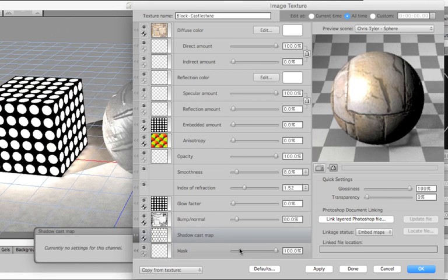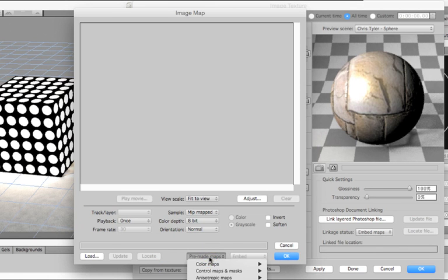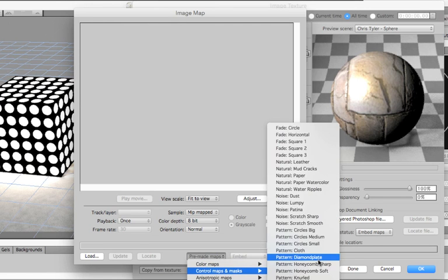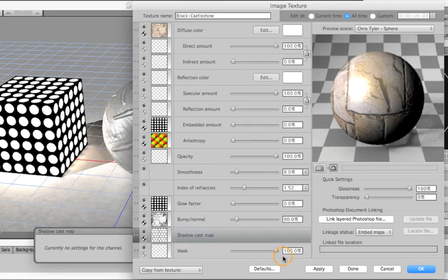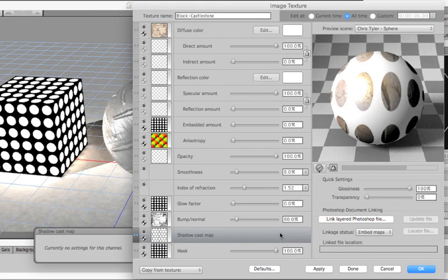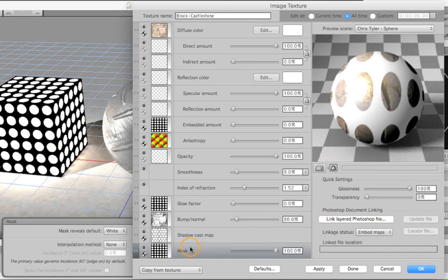As the name implies, you can use this channel to place in a map to mask the texture's effect. The mask uses the black areas to reveal whatever is underneath the surface. If there are other textures layered under this one on your object, that texture will be revealed. In the case of our preview model, there's no other texture under this one, so we have the option of revealing to white or invisible. The slider lets you adjust the overall effect of the texture.